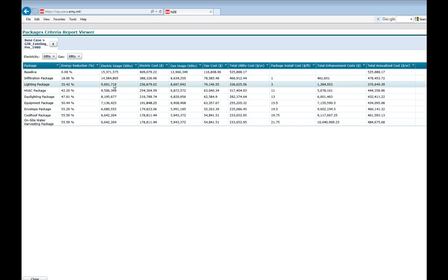We should also realize in cases like this that when we do reduce the lighting, we do get a benefit from that reduction. The lighting electric goes down, but know that this is an integrated solution, and so you'll actually see in some cases that depending on the climate zone and building type and all that, the heating energy will go up. So from the heat off the lights, you'll get a little bit of offset that you'll have to make up again on the heating side. And depending on the building, depending on the situation, this can be small, as it is in this case. There's a little bit of an increase, or surprisingly, it can be significant. So it's just to know that this is integrated and does account for that.